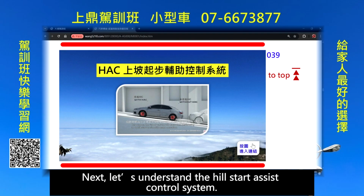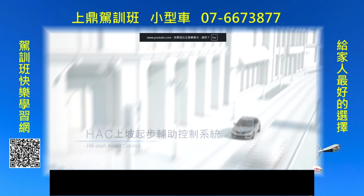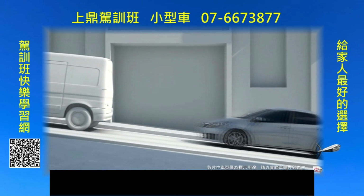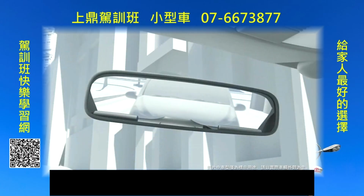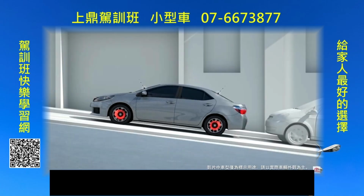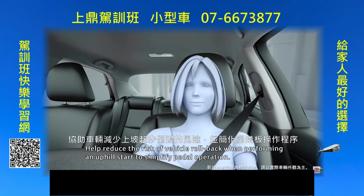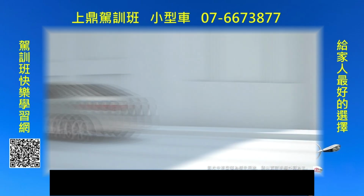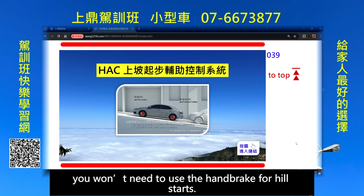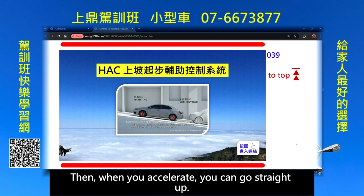Next, let's understand the Hill Start Assist control system. What is its operating situation? After watching this system, dear students, when practicing driving, if you have this system, you won't need to use the handbrake for hill starts. After removing your foot from the brake pedal, it will hold your vehicle in place. Then, as you move your foot, the vehicle won't roll back. Then, when you accelerate, you can go straight up.